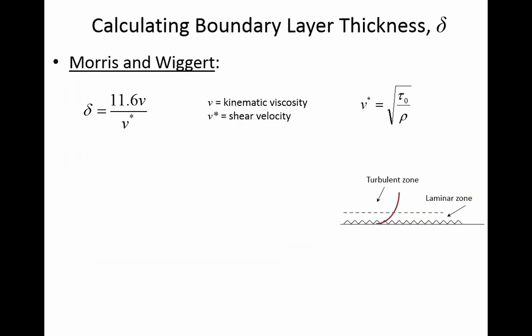Okay, back to the boundary layer. We're just talking about how different metals have different roughness heights. Here, these little ridges represent the grains, maybe in a cast iron pipe, or it could be the corrugations in a corrugated metal pipe. Whatever the material is, it has little bumps along its edge. You may have to zoom in really, really close to see the bumps, like in the case of a plastic pipe, where plastic pipes are really smooth.